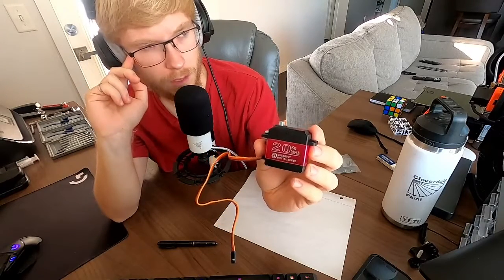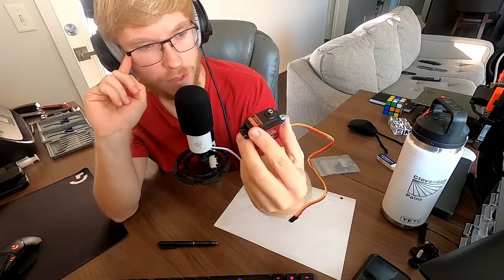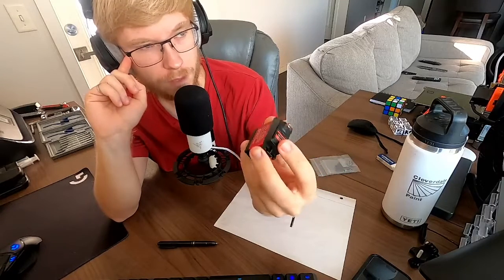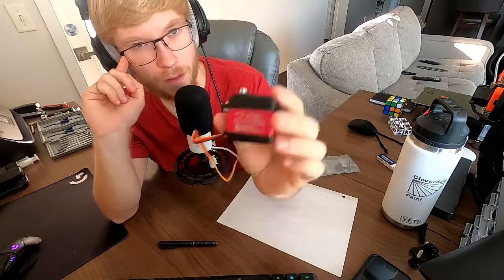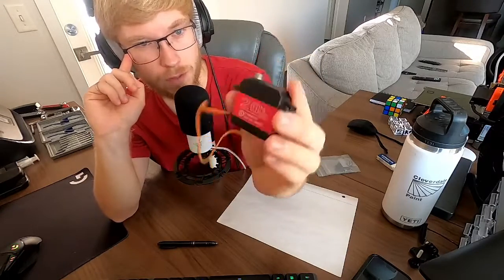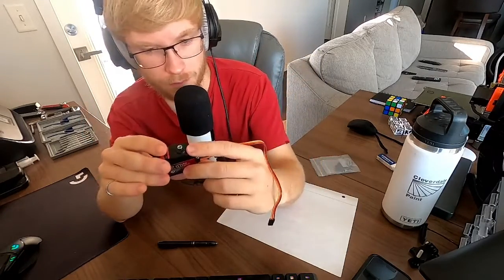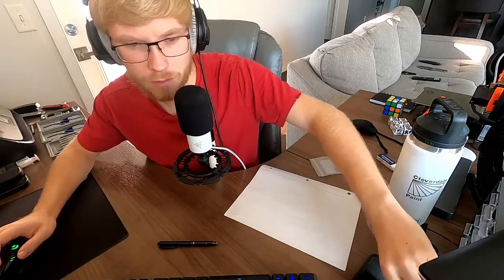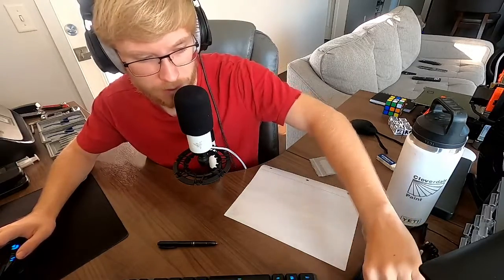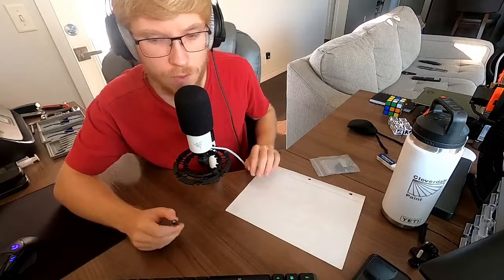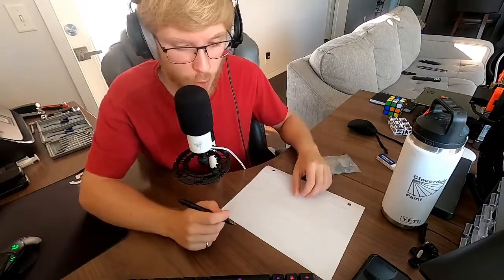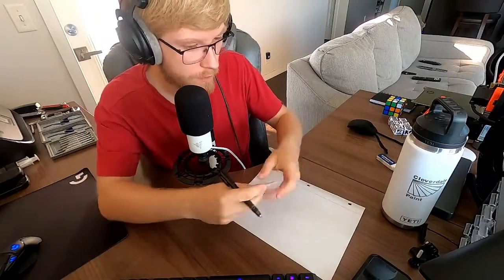I think I bought them off of AliExpress. I believe so, yeah. I don't think I got these off of Amazon. I have a bunch of 20 kilogram servos and then one 25 kilogram servo for the pivot servo at the base, because that's going to be where most of the torque is required. As you go along the arm, there's less torque required, naturally, as there's less force.